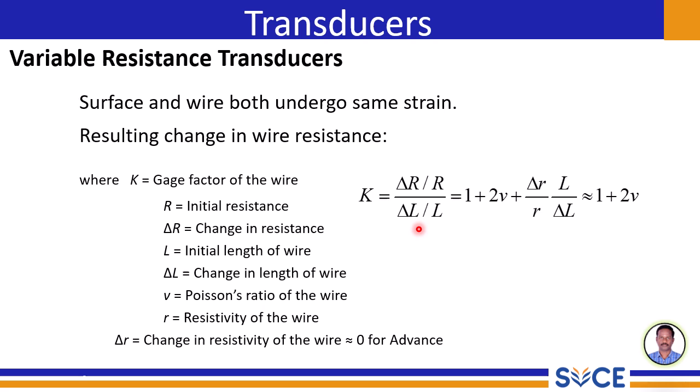In essence, by measuring the change in resistance del R of a strain gauge with a known initial resistance R and a gauge factor, we can accurately determine the strain experienced by the surface to which it is bonded. This ability to quantify the strain makes strain gauges invaluable tools in experimental analysis, and indirectly we are understanding the vibrational behavior of the structures.